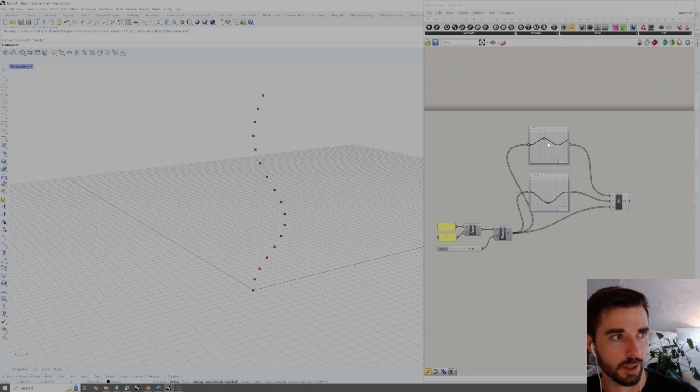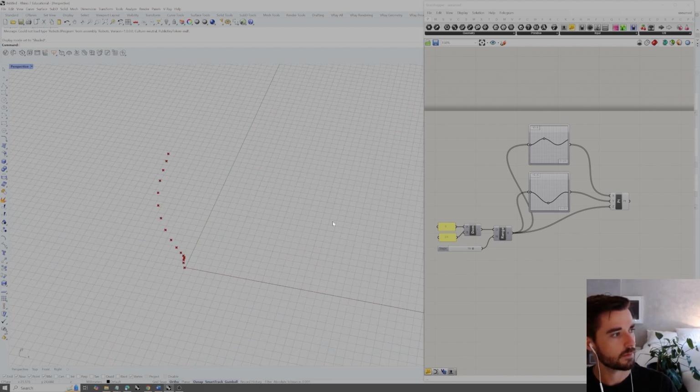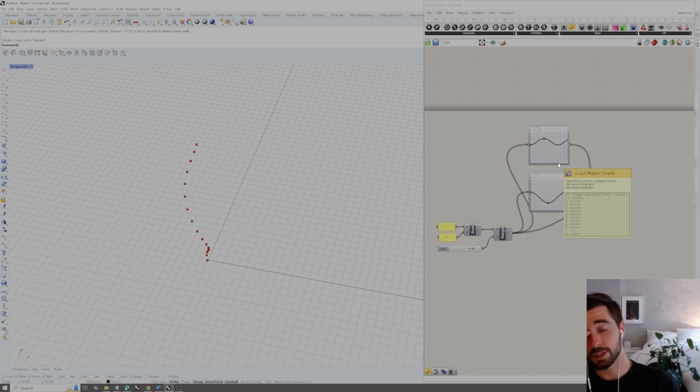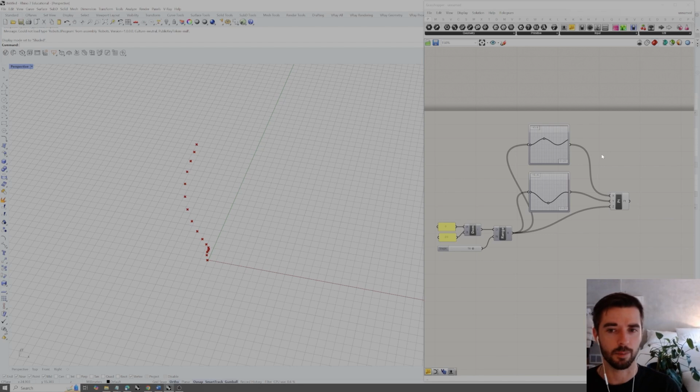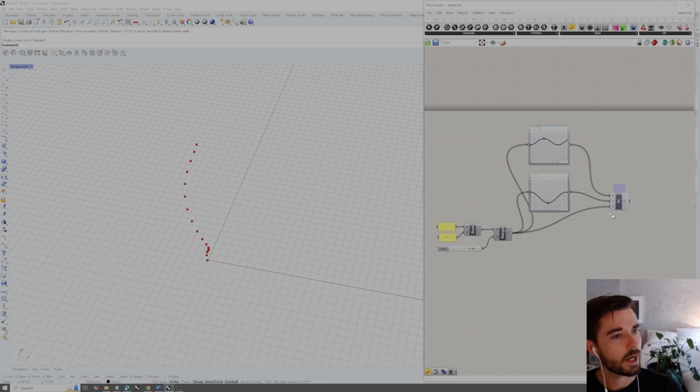Okay, by distorting both the X and the Y axis at slightly different periods. If we wanted to, we could also change these graph types to maybe something like Bezier, which might be a little bit easier to control in this example. But we can always do that at the end and come back to these graph mappers, right-click, go to Graph Types, and then select from any of these if we deem or expect one of these to eventually be easier or better to coordinate for something down the line. Okay. For now, though, this should be fine.